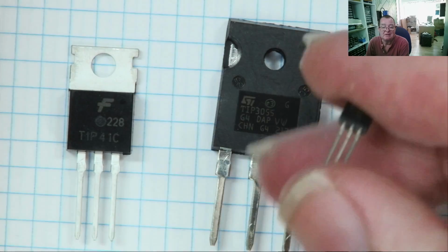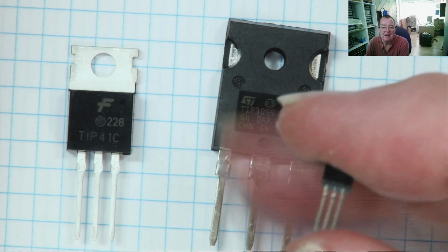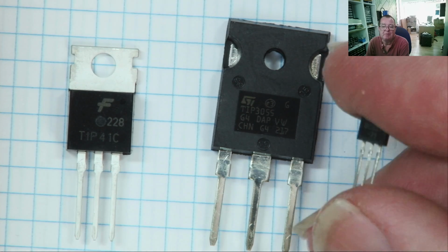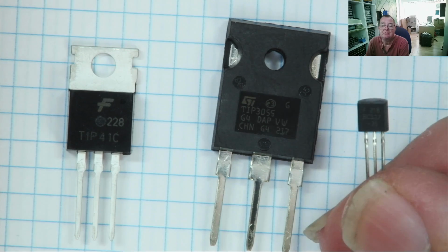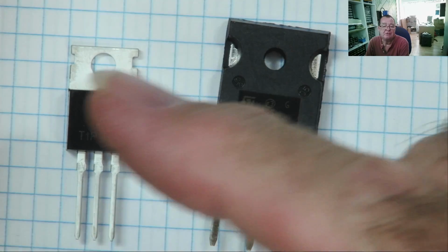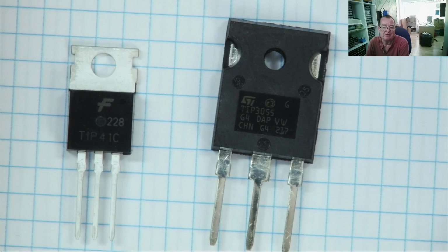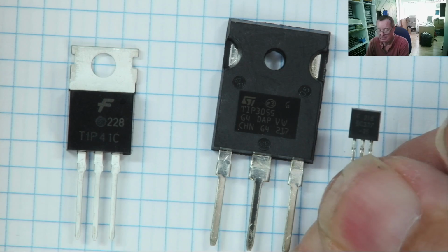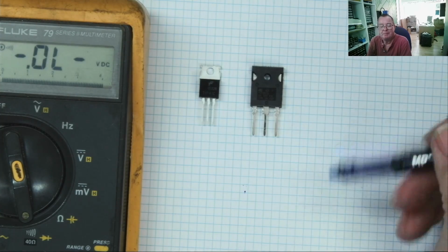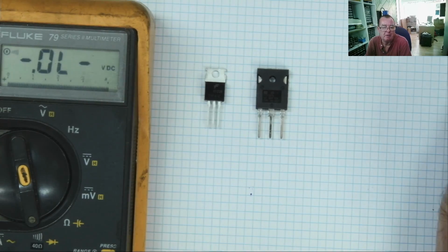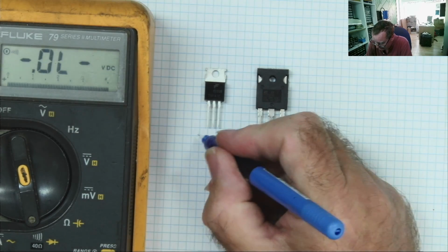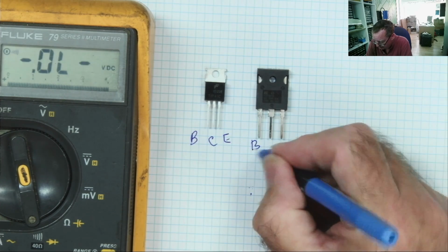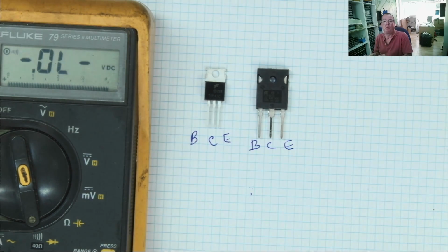Now, whereas these pretty much always you know the pin out, with these you don't. This package is using every possible combination of pin out you could imagine for different types of transistor. So let's look at these two, because we know which are base, collector and emitter, and see how they read. And let's see if we can work out the pin out of this transistor. Of course, I could have looked up this package name, but I'll wait for one of you guys to tell me. You should have known that. Okay, so this one, base, collector, emitter. This one, base, collector, emitter. That's almost always the case.